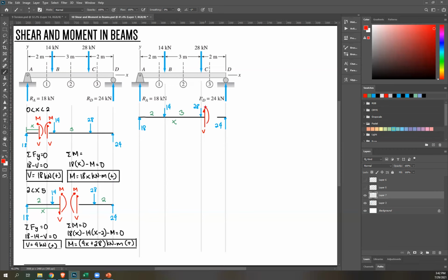Now if you don't wanna guess, to make things easier, you can just look at this portion. Okay? Sorry, this is going to create a counterclockwise moment here for the right side. Therefore, I need a clockwise to counter that. And again, for connecting members, should be the opposite sign. So there's already clockwise here, so this is going to be counterclockwise. Okay? So you can do that if you don't want to guess. Okay, so now we have these. So moment. Again, opposite. This is upward, therefore here it should be downward. And then you have a moment here.